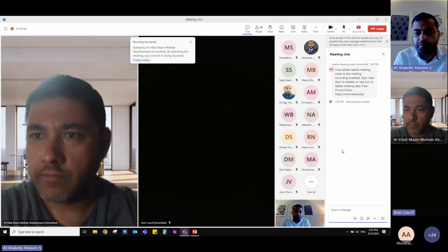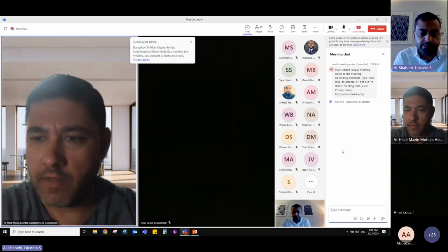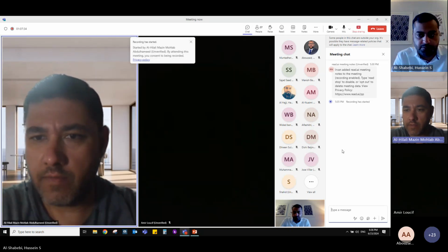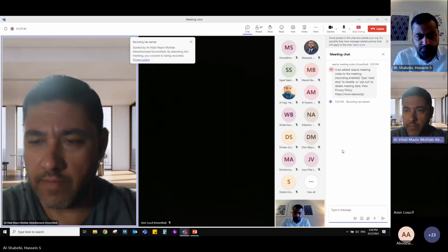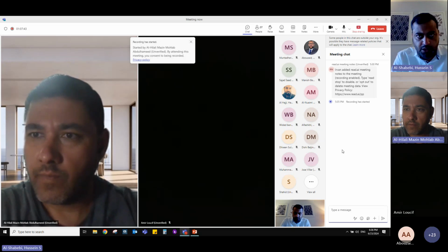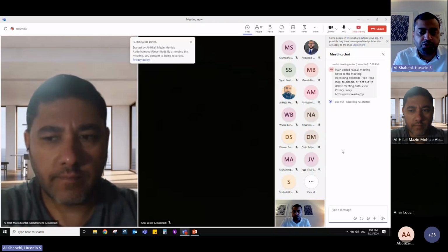No, it is 12.3 feet, including the centralizers, about 1 meter. So it has 6 arms, so it will have full coverage. As far as I understand, it has 3 sensors per arm. Yes, in every arm you have one spinner measurement, one optical, and one resistance.